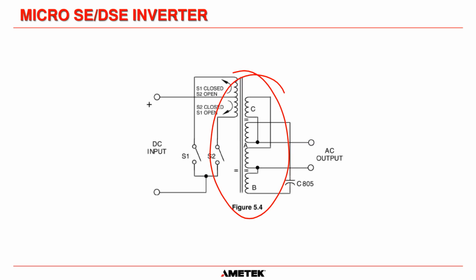Once you get the transformer into its saturation region, the output can't change very much. So that is what we're trying to do with the capacitor and the windings on this transformer. It's kind of complex, and we do have a white paper on our website that tells you more about how a ferroresonant or a CVT, a constant voltage transformer, works.